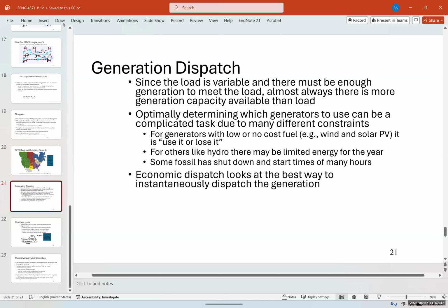It's not like you just flip a switch and turn off a nuclear power plant. It's a long procedure. Sometimes it takes up to 24 hours to shut down a nuclear power plant. You have to do it in a safe manner. That's the reason you had Fukushima, or Chernobyl, because it takes time for the core to cool down. You have to keep pumping water to keep it cool. It's not like a gas generator where you cut the fuel and it turns off. Nuclear power plants don't work like that.